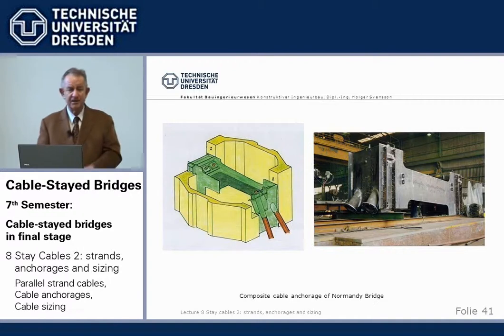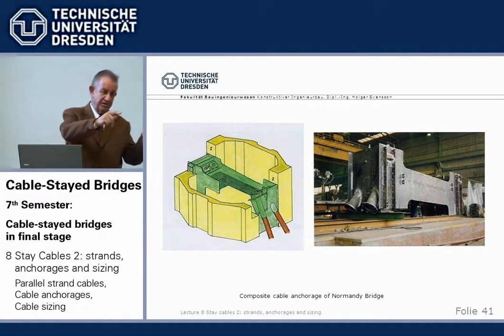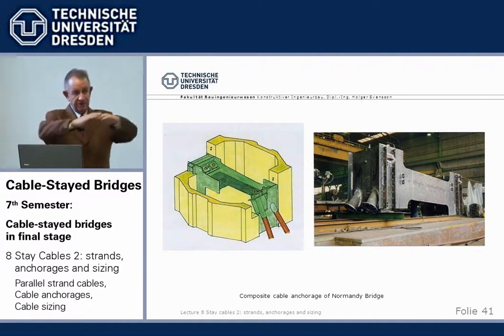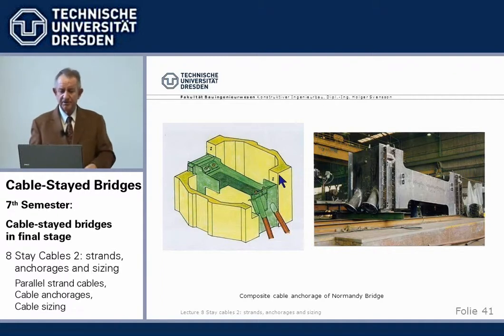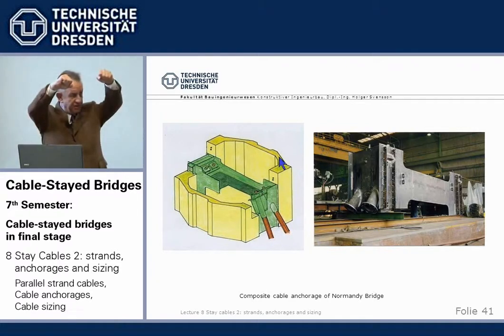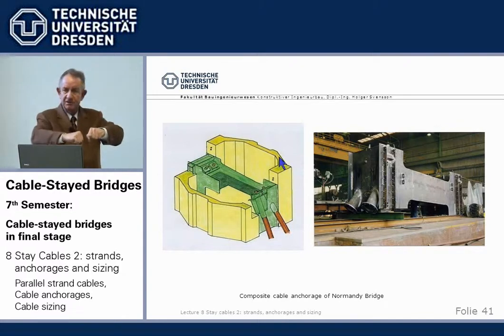Normally, we anchor the stay cables individually at the tower head. A disadvantage, of course, of a saddle with a continuous cable is if you have to exchange the cable on one side, theoretically, you can't do that. You have to exchange the full cable. Now, normally, we don't want to bend because of the fatigue problems; we want straight cables, anchored top and bottom. So then there is the current development since 10, 15 years. First of all, we use concrete towers, mostly, because it's cheaper to carry a compression force in concrete than in steel, period.